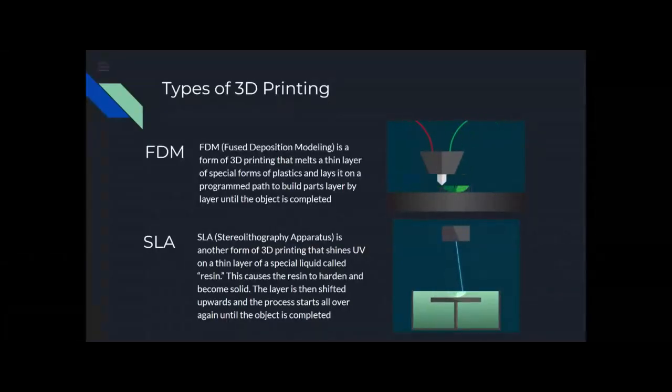So the way we really do this is the computer needs a way to be able to manufacture a three-dimensional object. So with FDM, you take in a plastic spool and it is melted by a hot end. That is like the tip of this machine right here that you can see in this little demonstration. What it will do is heat it to a specific temperature, and that'll cause it to flow. There is a little gear that pushes the plastic through, and that hot end is on top of a carriage that is attached to several motors that are all controlled by a computer that executes commands that you program.